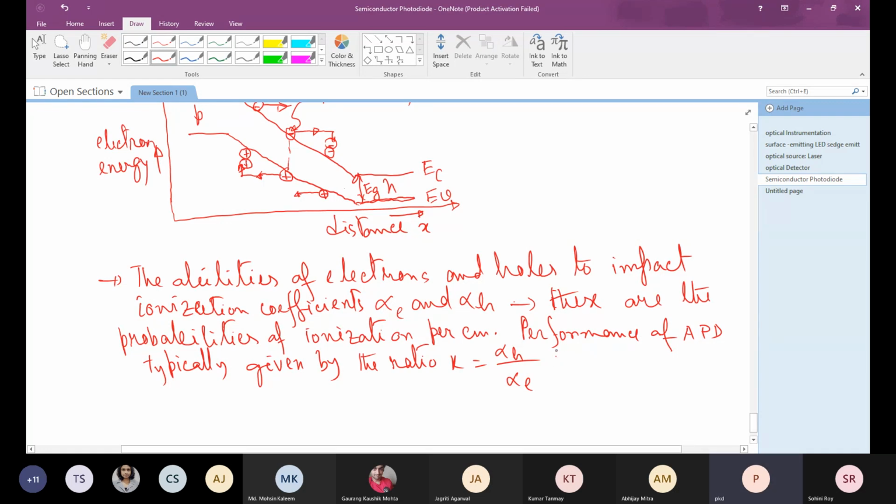Because if both are equal, then what will happen is, on both sides the ionic current will flow and there could be a pocket of circulating current in the depletion zone itself. That gives rise to accumulation of carriers which are not being efficiently collected by the external circuit.